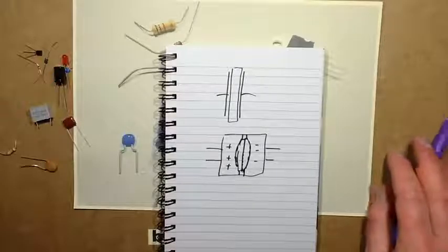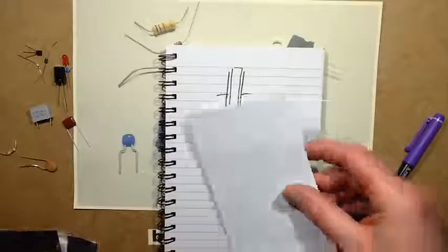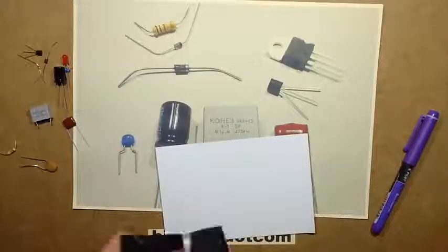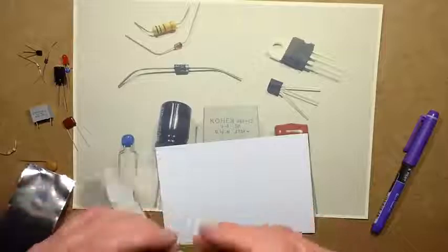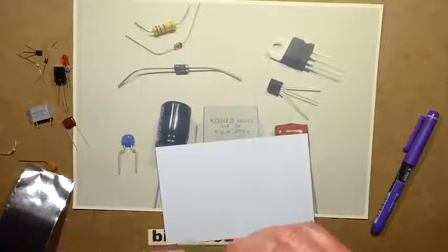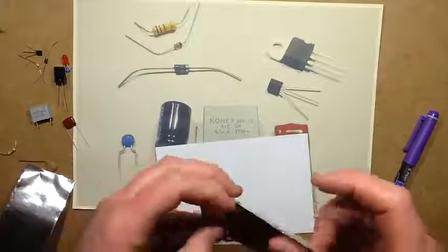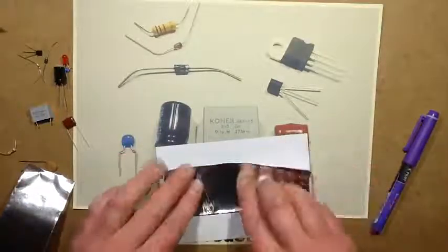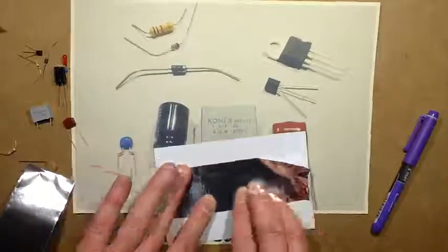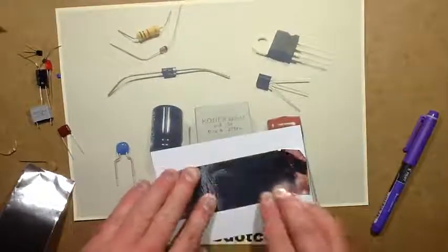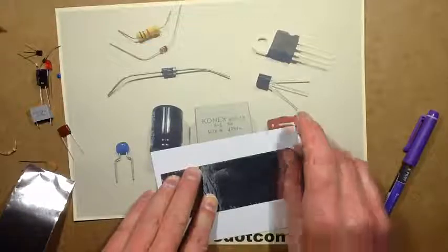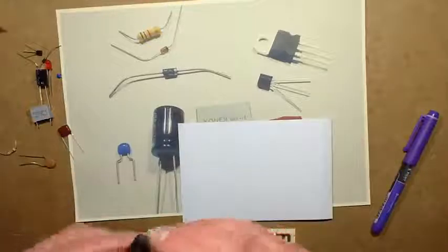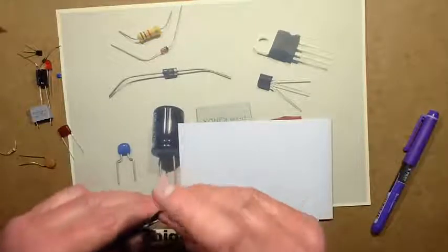So I've got a bit of cardboard here. This is a standard 6x4 piece of photo material. And I've got 2 bits of metallized film. So let's stick the metallized film on either side. So we've got a metal electrode and I'm sticking it onto the insulator, the dielectric. And this is old aluminium tape, I think, because it doesn't seem to stick very well. But that's alright, it'll do what we need to do. And then on the other side of this, I'll stick the other bit of tape, and that's the other electrode.